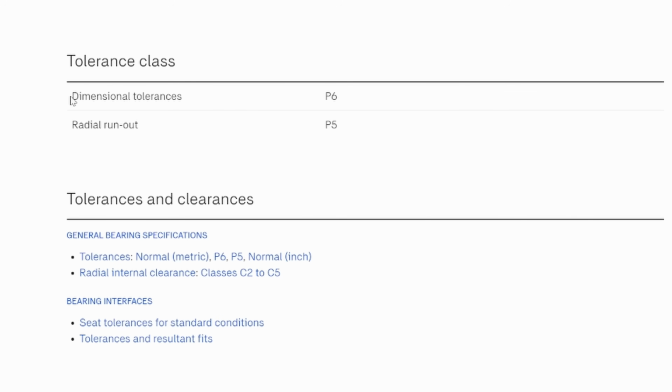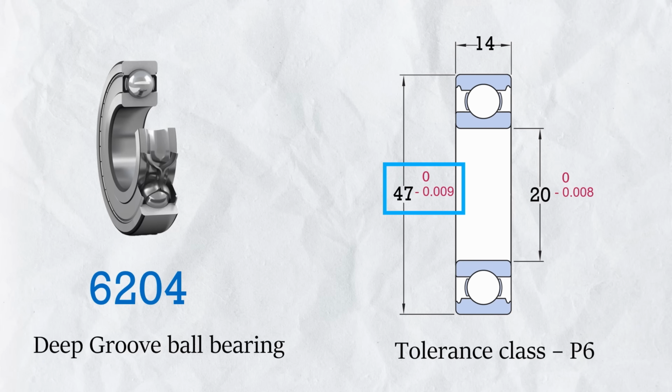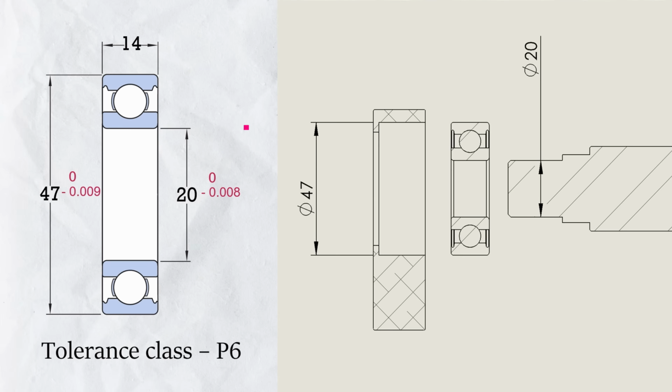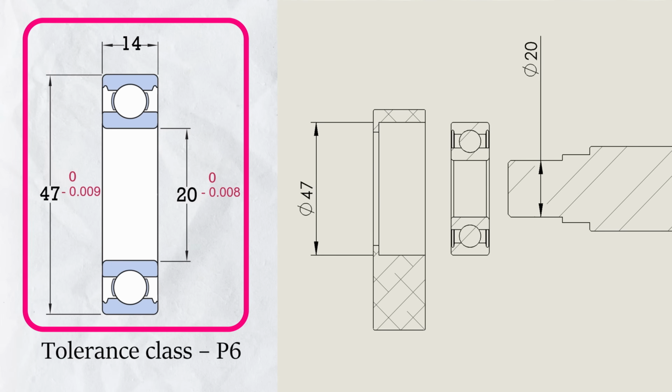If you want to understand more about bearing precision grade, later on you can watch this video. But the main point is bearing precision grade does not define bearing fitment. It simply defines the size tolerance of the bearing inner ring and outer ring. But we are here for the size tolerance of bearing seats, the recommendation or the formula of the size tolerance or fit for the bearing seat, not for the size tolerance of the bearing itself.